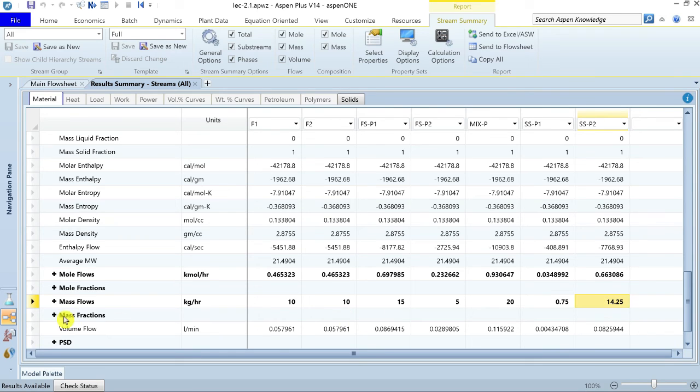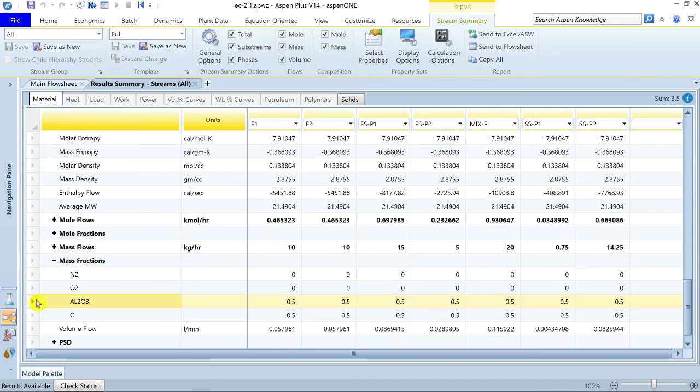It is important to notice the composition of the solid substream in the two streams. You can notice that the composition of the solids in all the streams is the same. So the substream splitter only splits the substreams between different streams without altering the composition of each stream. This means that regardless of the nature of the solid components, the SSplit has simply divided the solids between the SSP1 and SSP2 streams. Otherwise, for practical application, it might be possible that the individual physical properties of the components play a critical role in their separation, even having the same particle size distribution.